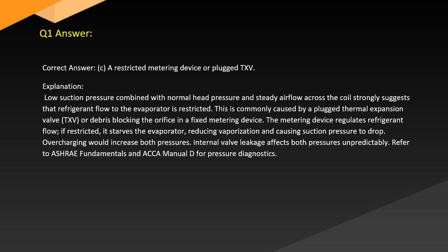If restricted, it starves the evaporator, reducing vaporization and causing suction pressure to drop. Overcharging would increase both pressures. Internal valve leakage affects both pressures unpredictably. Refer to ASHRAE Fundamentals and ACCA Manual D for pressure diagnostics.